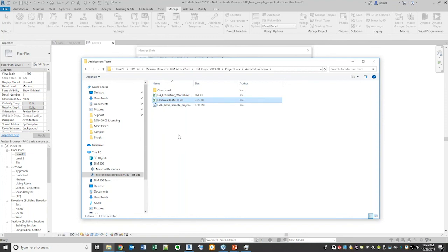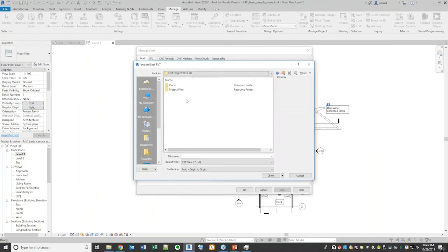So you do have to keep in mind this works similar to Dropbox or Box, where the last save wins. You should not open this directly to edit a model in Revit. Not recommended. I think the system would let you do it, but I think that you would run into a lot of problems. It would be similar to trying to open a Revit model directly over Dropbox. There's no file locking, there's no simultaneous coordination, you're just going to corrupt the model. So just be careful about that.